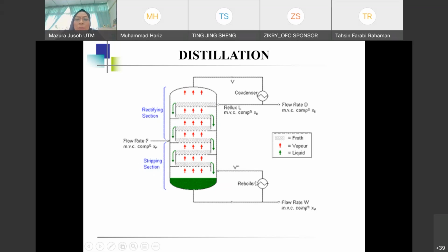And this is a reboiler. It's called a reboiler because you'll have a bottom product over here, and it will be boiled to the temperature that you set, and it will go back into the column, and then it will be a loop without stop. If it's a boiler, it will not go back in there. This is a reboiler because it's going to be heated again and again.